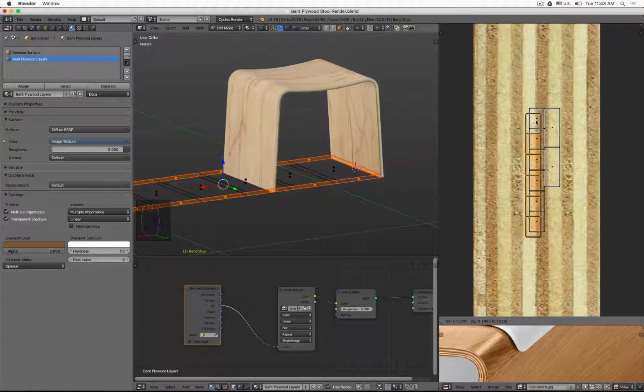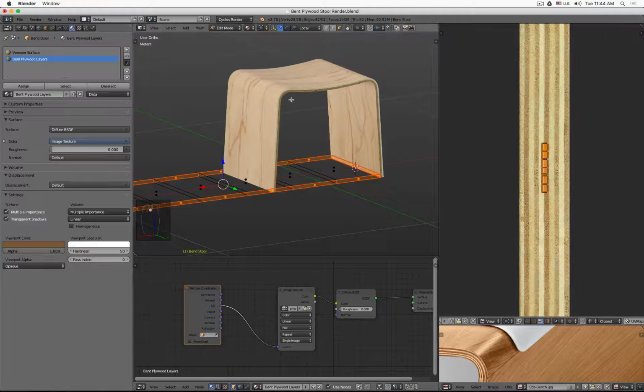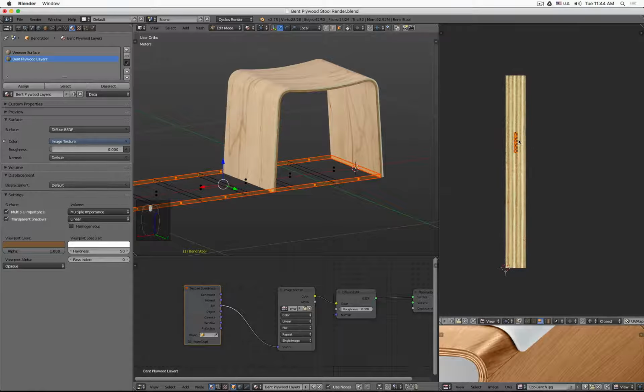So G and snap to maybe this vertex, U and U, G to somewhere else, G and snap also to there. So I hold Control. Okay, so now all these faces are all overlapping. That's okay, because they're all at different faces. I also down here have sharp edges, so not a big deal.